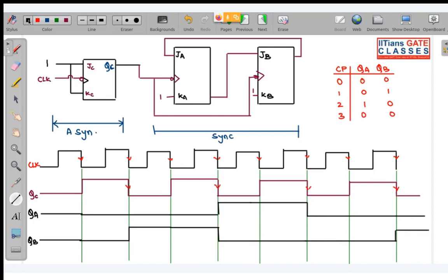Okay. So now let us write over here what are the counts we have. Over here we have 1 0 1 0 1 0 1. Over here 0 0 0 0 1 1 0 0 0. Over here 0 0 1 1 0 0 0 0 1. So out of QA, QB, any one of the following can be MSB because both of them are toggling equally. So I am taking QA, QB and QC, because QC is toggling the most.